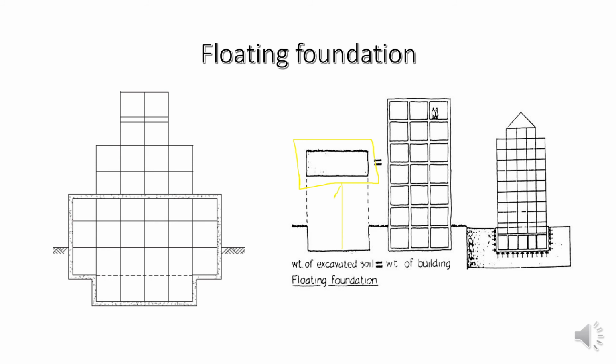This portion is the excavated portion. The weight of the excavated soil should be equal to the weight of the building. So the weight of the building should be equal to the weight of the excavated soil.